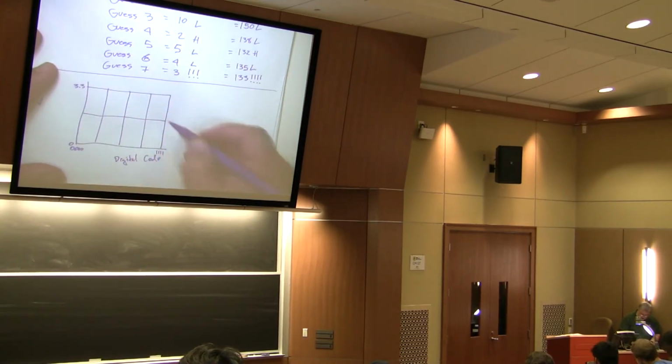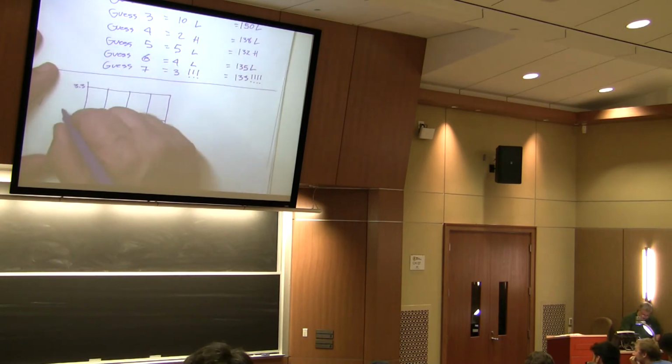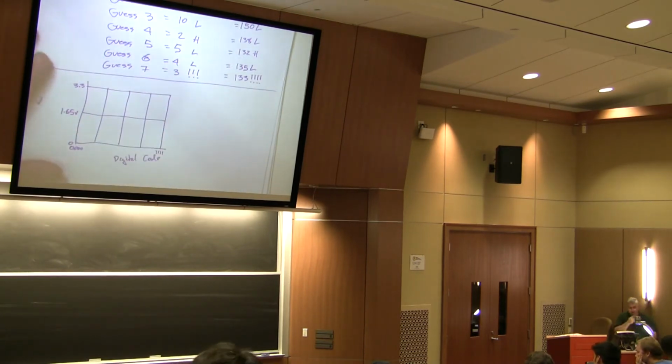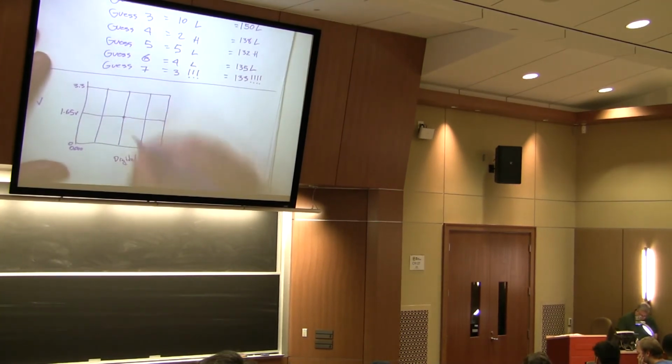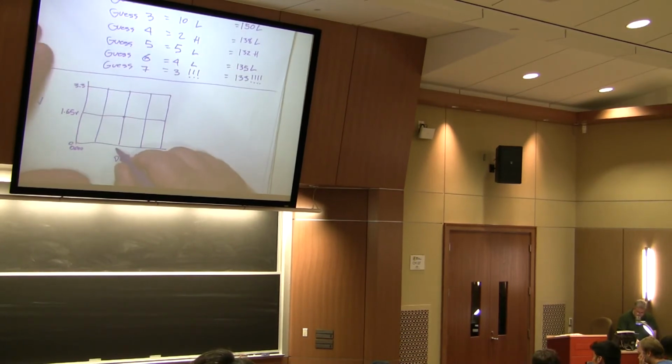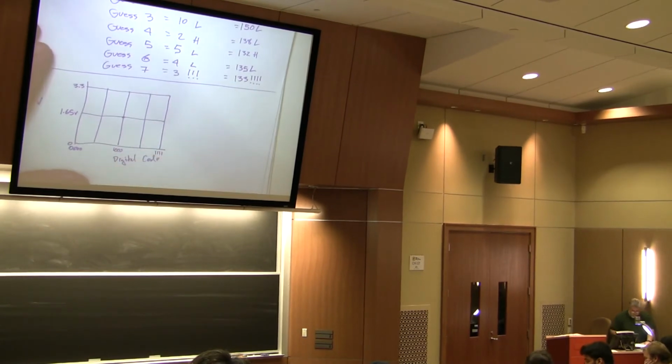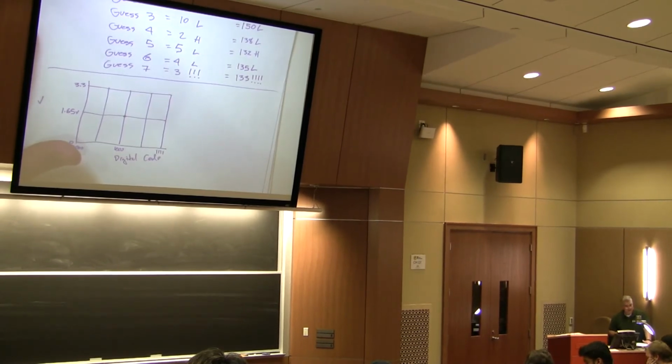one thing I know is that halfway in the middle is going to be 1.65 volts, right? So my expectation is that the digital value right in the middle is about 1000. Is that correct? Yes? Yes?